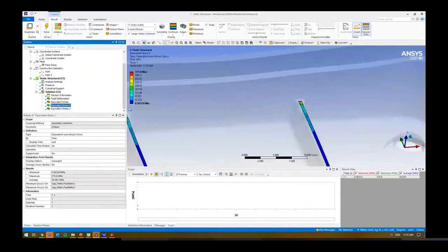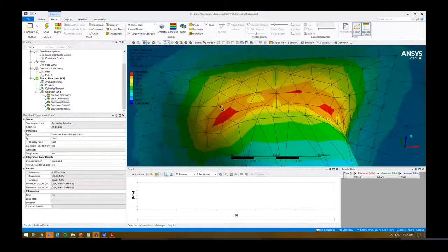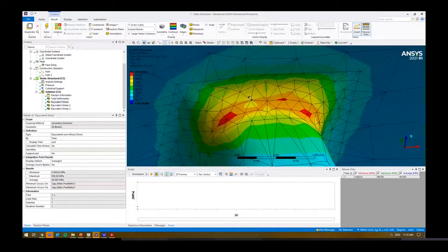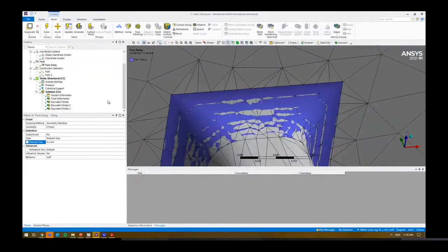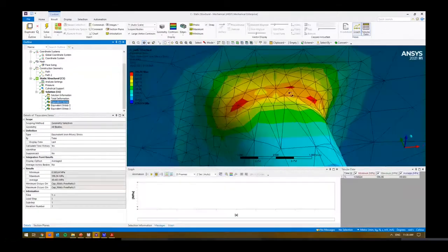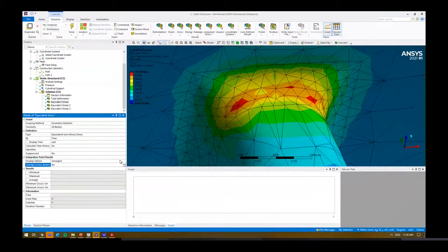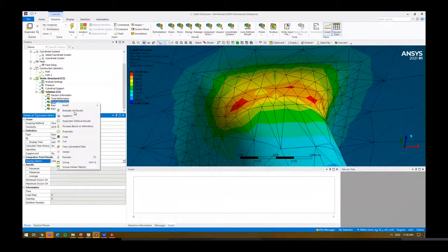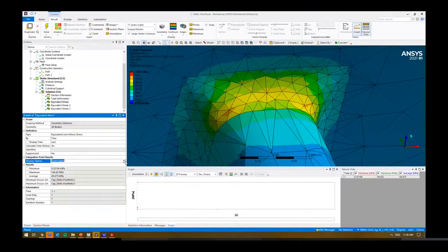Right. So going back to this problem though, looking at what's happening around here. Now we've got a bit of a better stress gradient across there, right? We've got a couple more elements to pick up what's happening. Still probably want to go back and make some additional changes, maybe change this to make it a little bit smaller, just to pick up better stress around that region, right? Again, if we go to say things like the averaged, we can have a look at it. So now again, we've got some better distributions.